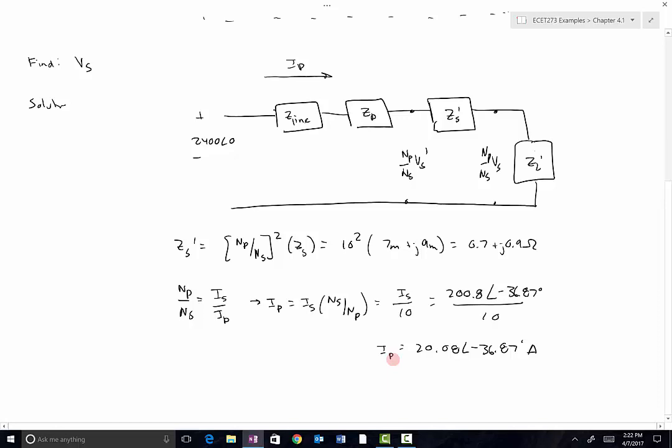Now we can use any common technique of circuit analysis to determine the value that we're interested in. We were asked in this problem statement to determine the output voltage across the transformer's secondary, so we're interested in eventually getting to VS. There are multiple approaches to solving many of these problems, but I would just take 2400 minus IP times those three impedances in series.